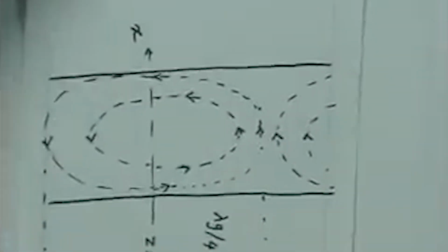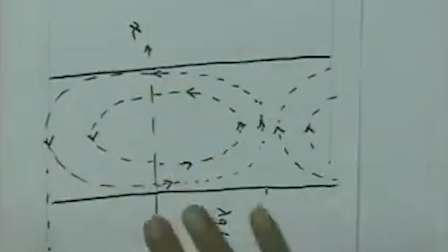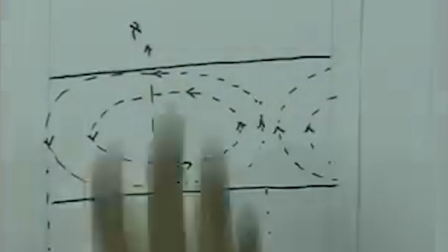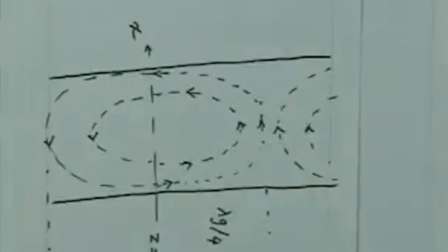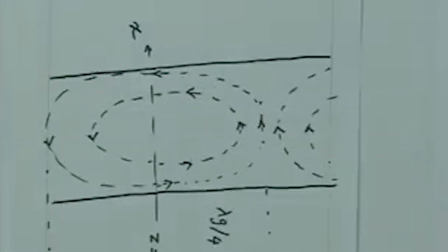So, if I look at the waveguide which will look like that, this is a parallel plane waveguide. The magnetic field lines look like rolled carpets which are stacked inside the structure, and they are of infinite length, which are perpendicular to the plane of the paper. That is the way the magnetic field lines will be distributed.